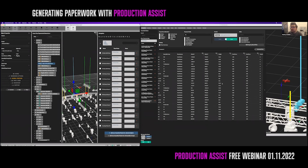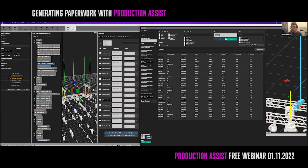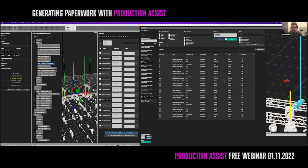So right now what we're doing in here is we want to modify this as well. I want to remove the chain shorten value as this is just too much information in there. I want to remove the hook force because I don't want to tell how much load actually goes into the hoist, but I want to show how much load goes actually into the roof. And I remove the weight of the hoist because that is not really relevant in here.